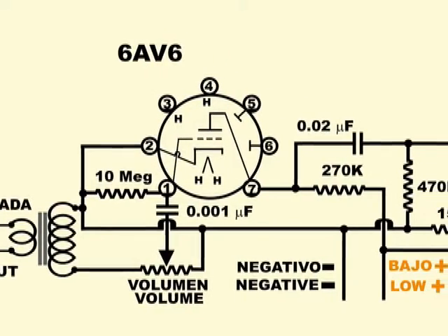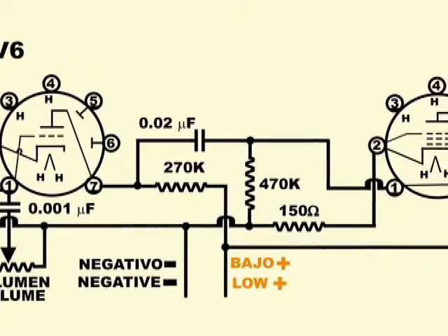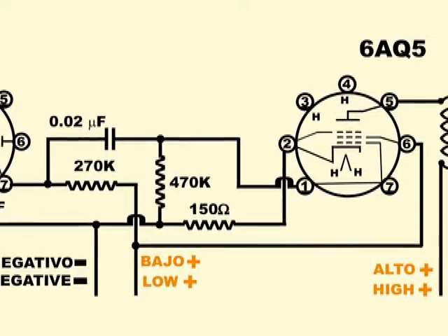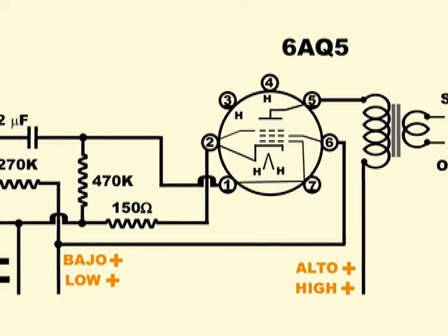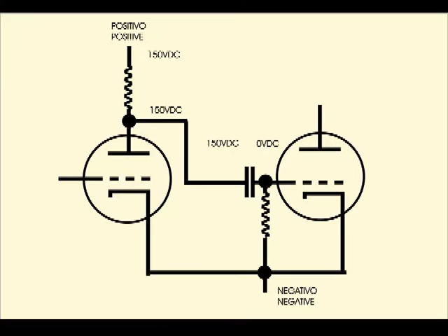The triode tube acts as a preamplifier, which in turn drives the output tube, providing enough power to drive a 5-inch speaker. Let us now look at the way the triode output signal is coupled to the pentode control grid. The coupling is done using a capacitor.